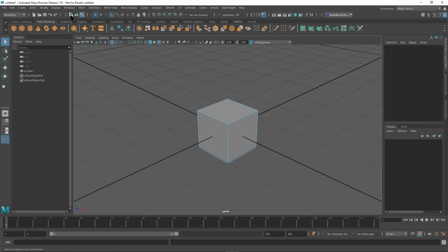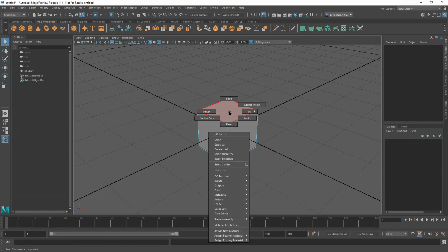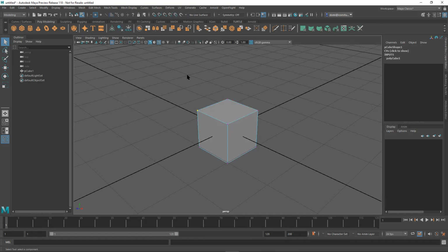And then hierarchy mode is when everything's grouped together into a hierarchy. Okay, so that's where you would access these bits if you're just working on screen. So it's right mouse click on the object, okay? And then you can pick whatever selection tool you want to use, and then all your transform tools work at that level.